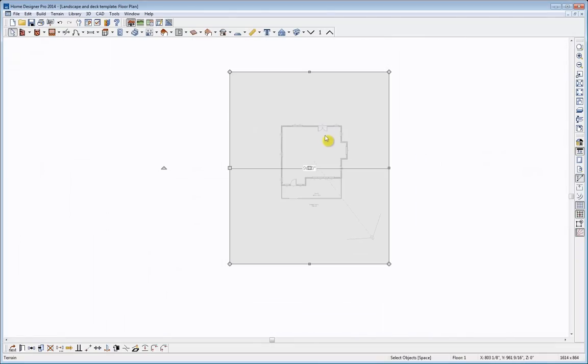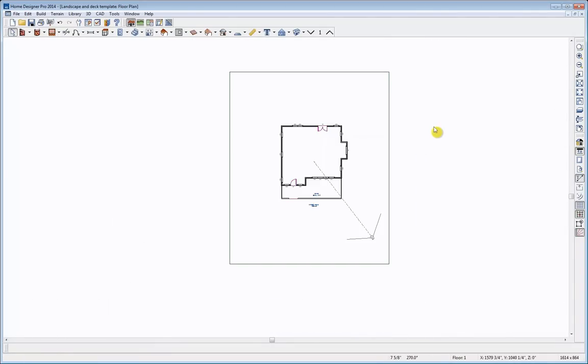There is another way that you can work on the terrain as well, especially if you have very specific setback requirements for your terrain. This can be a really handy way to make sure that you're meeting those. So I like to use the end-to-end dimension and simply go from each edge of the house to the edge of the terrain, draw them out, clicking on the edge of the wall and releasing once I hit the terrain.